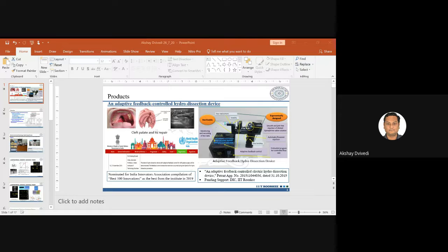So what you need is high frequency sparking. Simultaneously, you also need a high intensity of each individual spark. And if possible, that intensity should be more or less uniform throughout the process. So let's say, if you carefully look at this very small oscilloscope image which I have here, you will identify that the frequency of sparking is quite high, and the majority of those sparks have the same kind of intensity. So when you apply ultrasonic vibration on the tool, the film actually changes its shape.